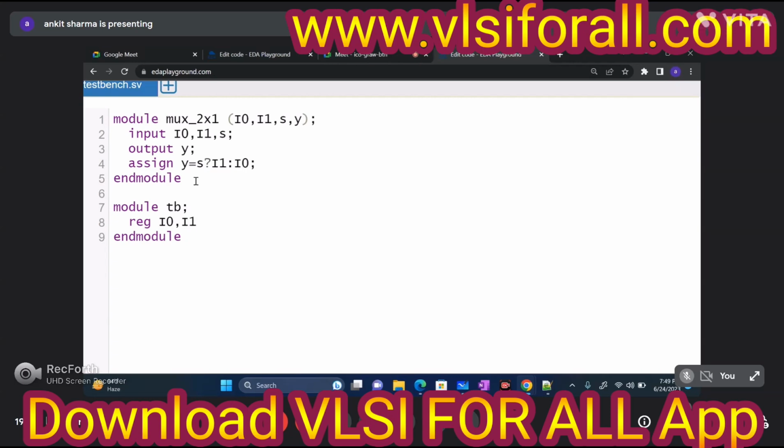Let's suppose we have I0, comma I1, and here I can give some wires of Y, and here I can do instantiation of mux 2 cross 1, and I can do mapping as I0, I1, select, Y, and it should also have that select line.